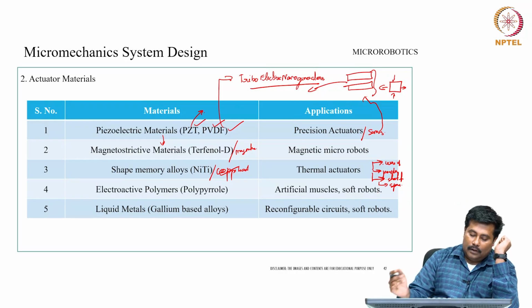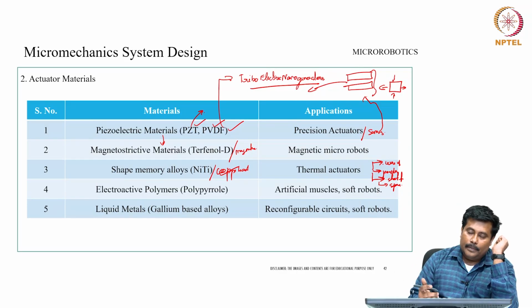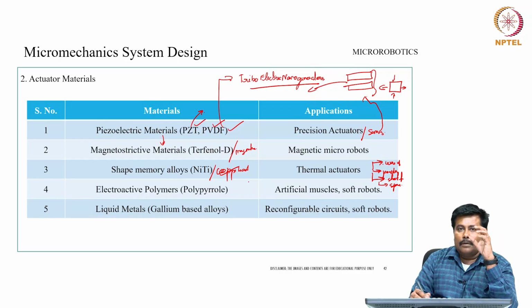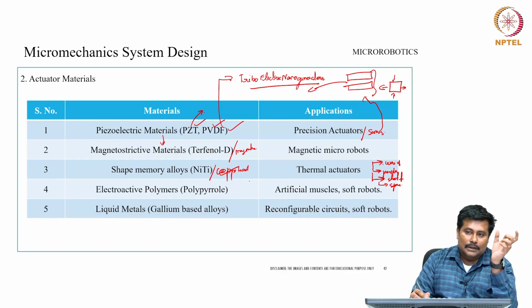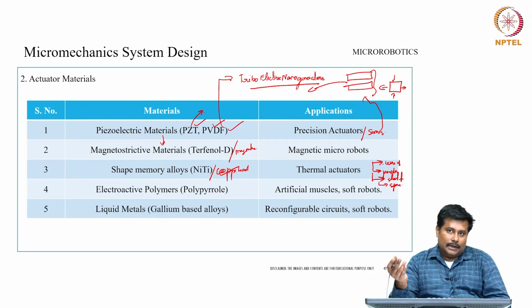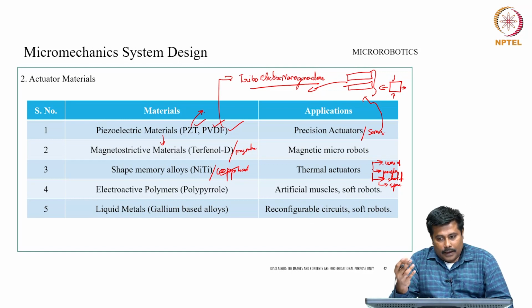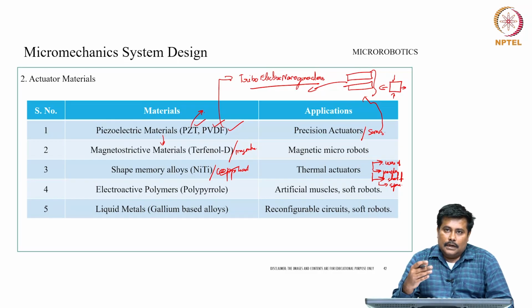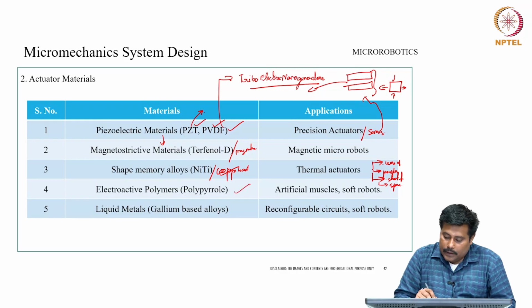If you closely observe these shape memory alloys, it basically depends upon the overall actuation condition, and based on that we classify the structure. If we have a working window in the range of 80 to 130 degrees Celsius, ideally we go for nickel titanium based shape memory alloy structures. In certain cases, if we have a range of 250 to 350 degrees Celsius, we go for copper based shape memory alloy structures.